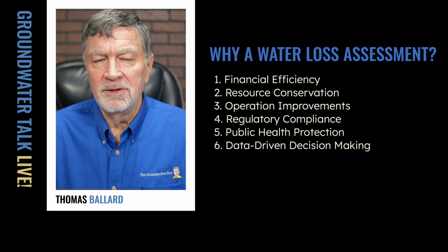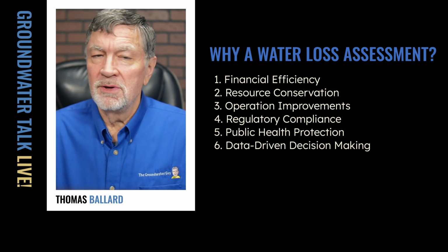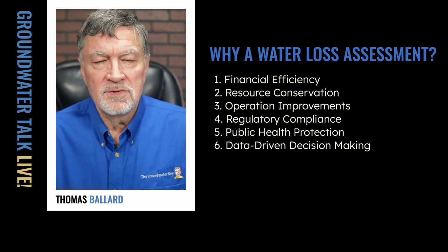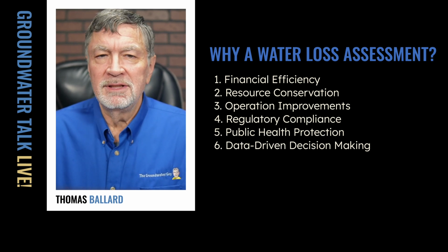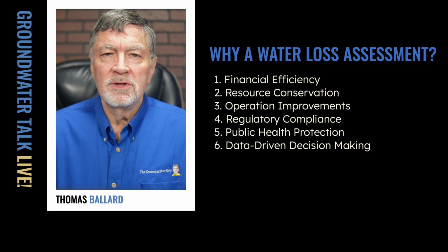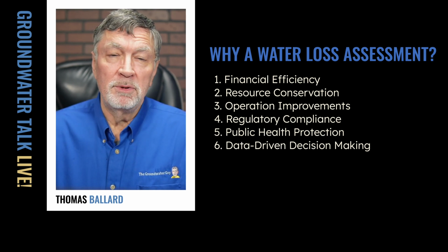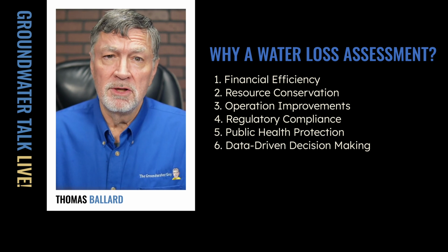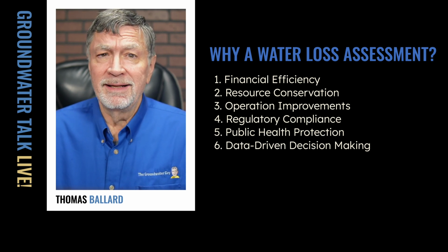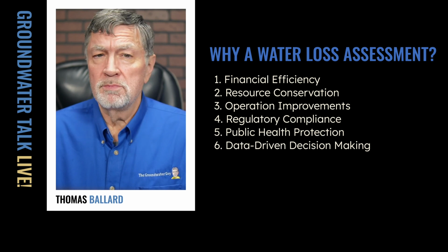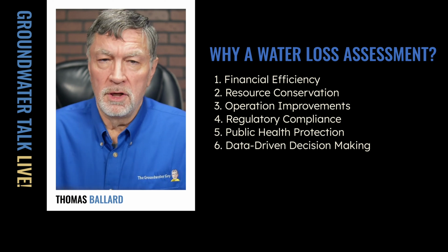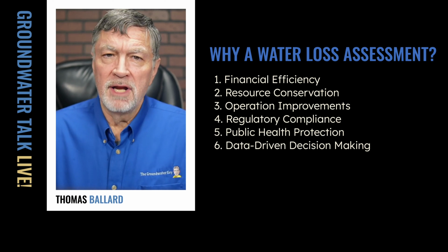Now, older meters are going to lose their accuracy a little bit as they wear down, and some of the sensors in there get out of calibration. So you're probably going to have a plan that's part of your asset management plan to replace meters on a regular basis and document where those problems are occurring, because meter inaccuracies can be a source of apparent water loss.